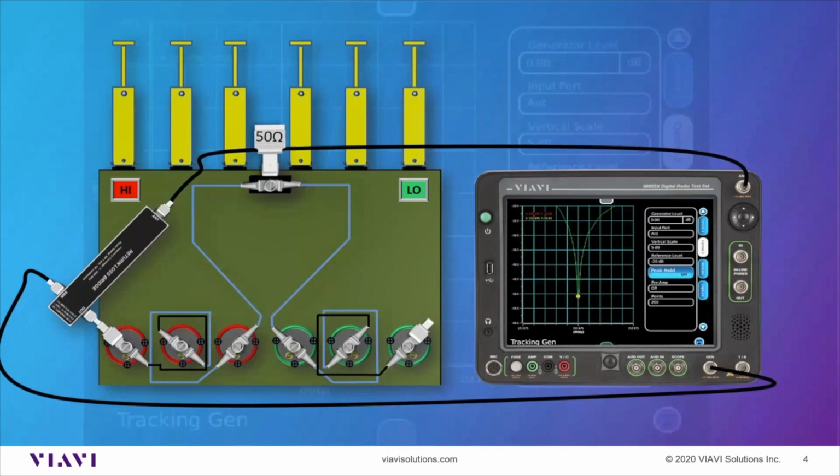Now, if you're just doing a PM on a site, the thing to do is just to check the insertion loss and make sure that you've got good isolation. So you would just use the process of setting the reference for the high pass or the low pass, and then checking the insertion loss, and then changing your reference level and checking the notch, to make sure that you've got good depth on the notch. And that process would only take you a couple of minutes really with the service monitor.